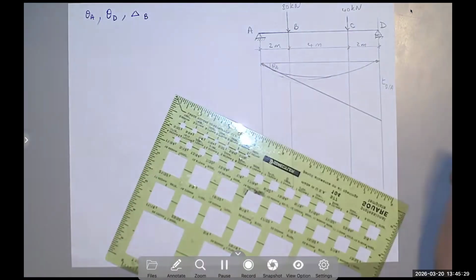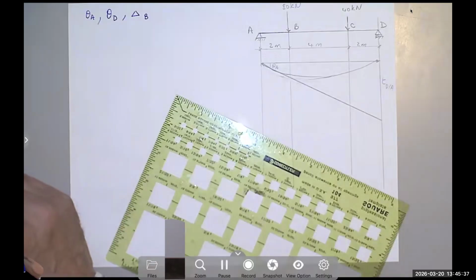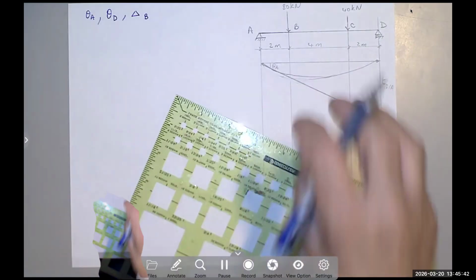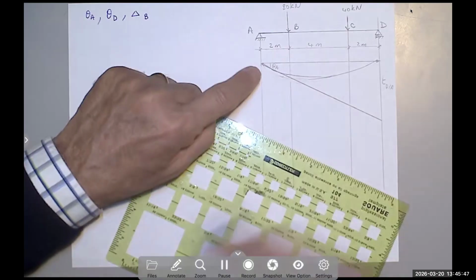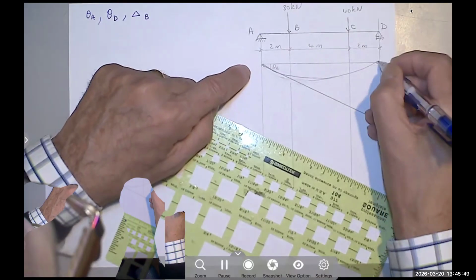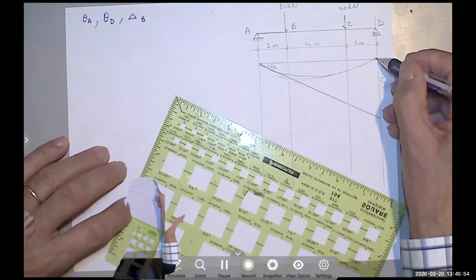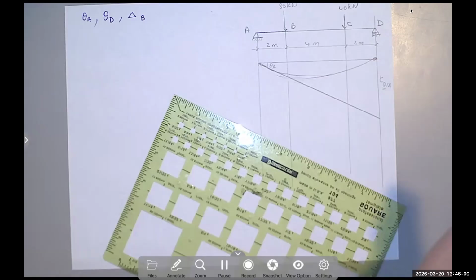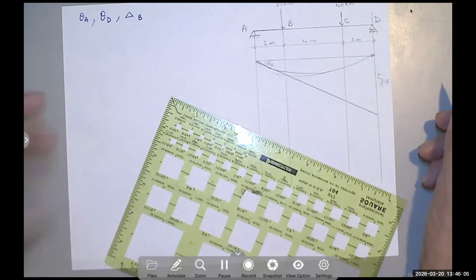But what is T D sub A? When we draw the bending moment diagram, you take each part of the bending moment diagram and multiply it by the distance of its centroid from D, because D is the first letter, so it's the deviation from D. If it's only one triangle, just multiply this triangle by how far the centroid is from D, which is 1/3 of the base.